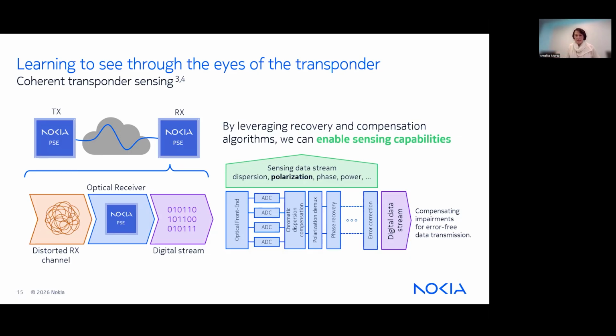During the compensation of the physical effects, there are also some data concerning the polarization. So it is possible to take this information to record and observe any changes about the SOP variation. This means that the sensing is done by extracting information from the DSP that is recovering the data associated with real traffic transmission.